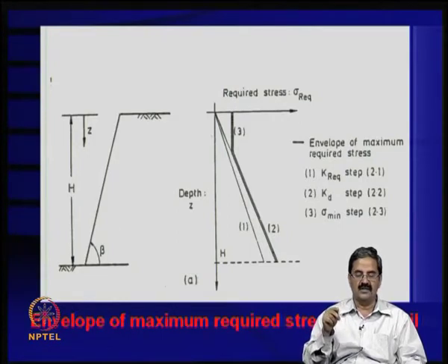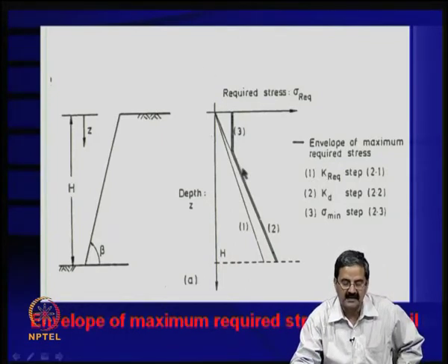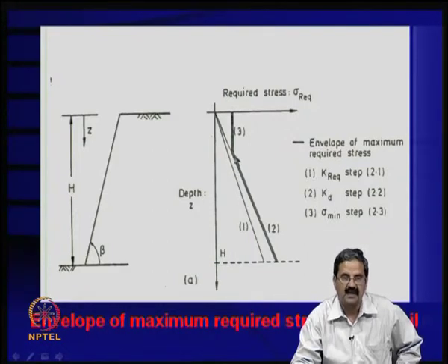So what we should do is assume that the whole force is acting, but there are some small changes here. From bond and reinforcement angle considerations, there is a small correction factor you have to put in. Because of this, the required reinforcement force will be a little higher.